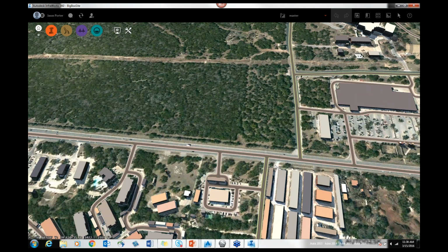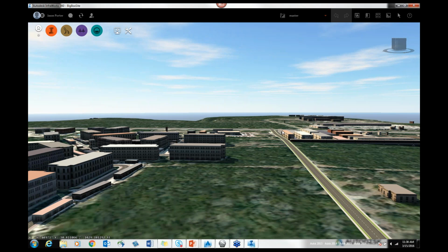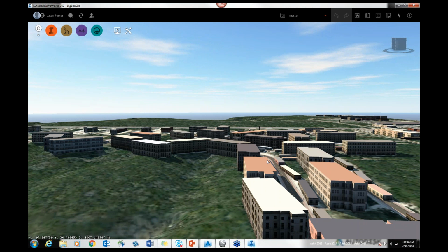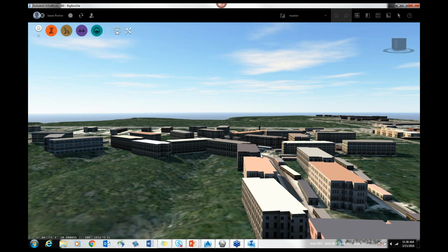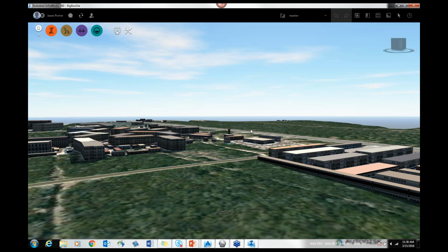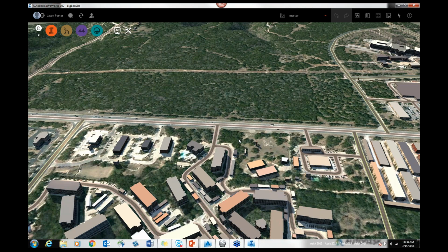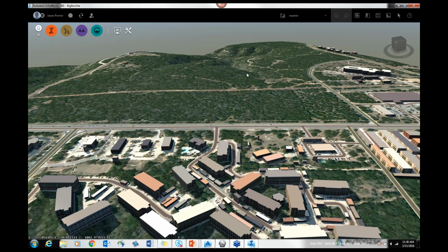My building locations, and the fact that they're there, have come in from GIS data as well. Now, they will not look and act exactly like the buildings that you see. It gives them some sort of a random facade in order for the buildings to just look like buildings. And notice they're all the same height. That's a discussion for a different day. But as you can see down here in the background, I have terrain and the aerial image.